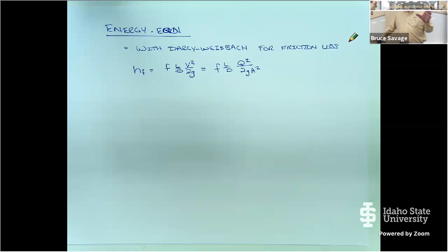And in our discussion, he said, you know, the equation breaks down. And I was like, well, which equation? He said, Hazen-Williams. And I said, you try the Darcy-Weisbach? And he said, no, I don't do that. So I looked at it, it breaks down too. Well, when I say breaks down, the Darcy-Weisbach predicted pretty close to the Hazen-Williams. And so I started doing a little digging. Turns out this is a well-known phenomenon, and I'd heard it in the past, I didn't remember much about it, that large diameter pipes have less friction than predicted.